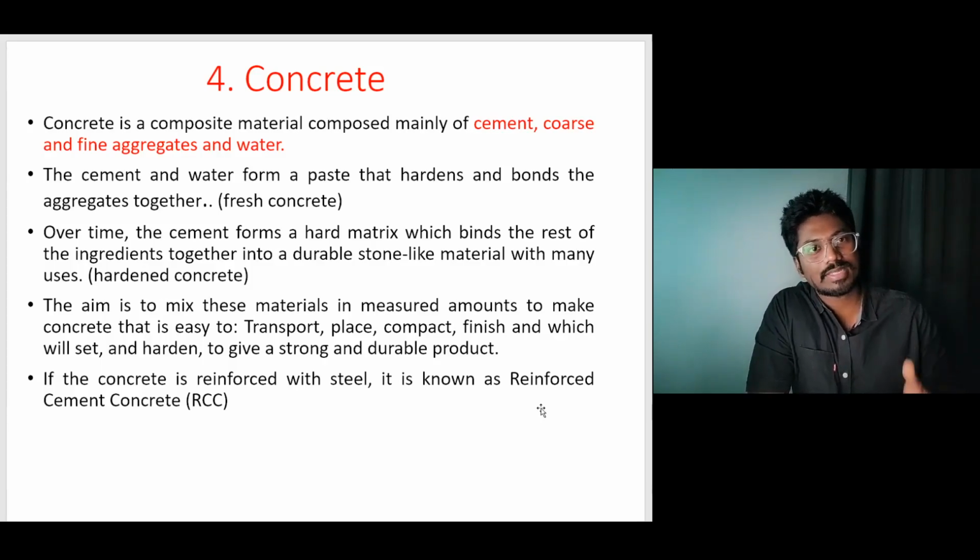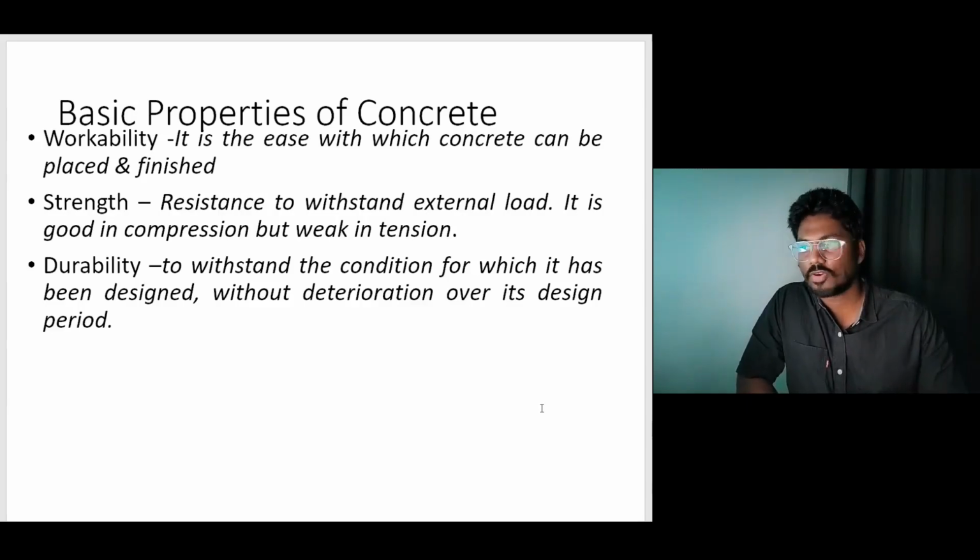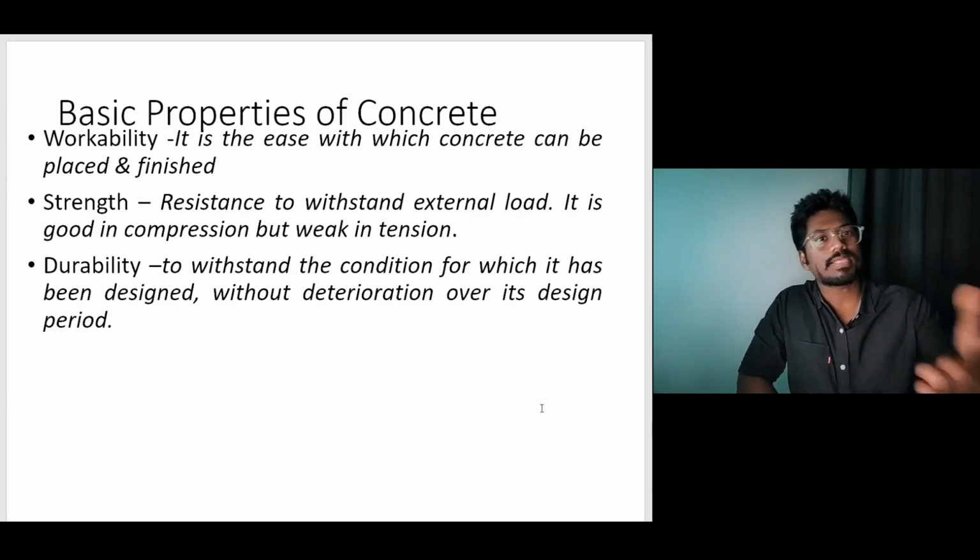If you have steel rebars or steel elements inside normal plain cement concrete, you can call it reinforced cement concrete. Now, basic properties of concrete. There are three basic properties of concrete. Number one is workability, the ease with which the concrete can be placed and finished.